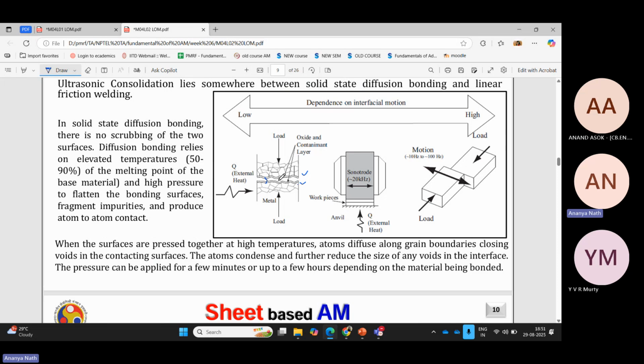The valleys will come later, but the peaks will be joined first. This is how the vibration gets transferred from one metal surface to another. By peak joining, the whole surface will eventually be joined. And this joining also takes place by diffusion bonding, like the peaks are getting diffusion bonded together.